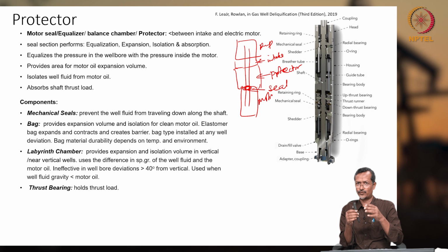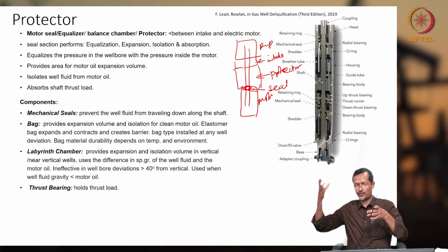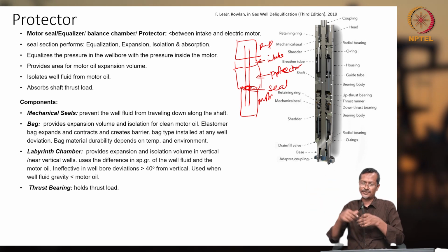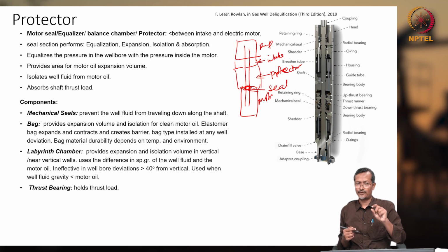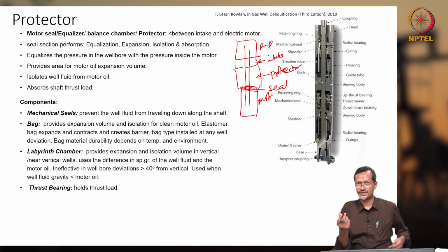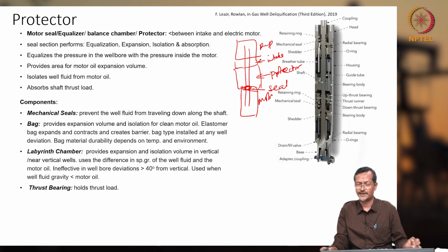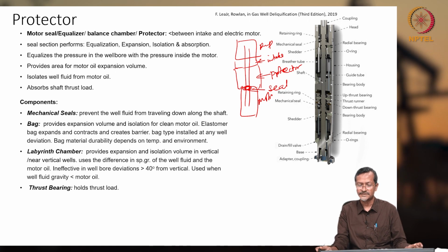Again, at a certain time your pump is not working, the temperature is lower, and outside fluid enters. High temperature fluid will try to go out, and lower temperature fluid comes in. Because of temperature, fluid will get exchanged, and wear and tear is also possible. Once fluid is exchanged, your system will burn. So maximum motor failure occurs because of seal failure in a submersible system.